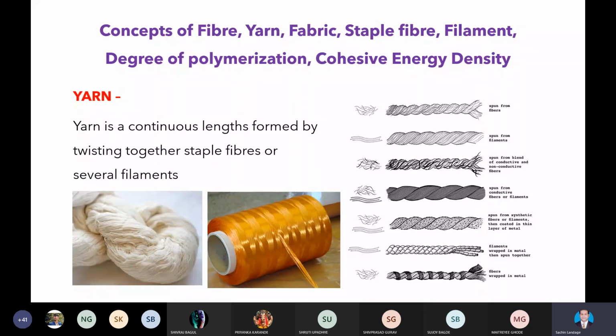For example, spun yarn. To have the spun yarn, again we are using various types of spinning technologies, like rotor. We can have the carded yarn, the combed yarn, the compact yarn, but that is nothing but the open end or the ring spun yarn. Open end or ring spun yarn is mostly used for short staple fiber, where we convert the short staple fiber into continuous yarn form. That is endless. Depending upon our requirement, we can convert it into the required length.